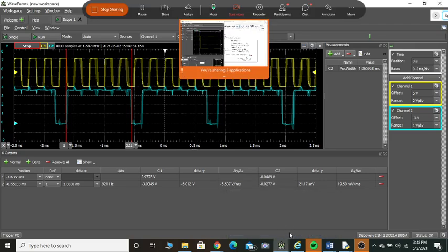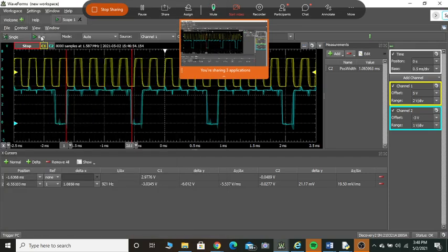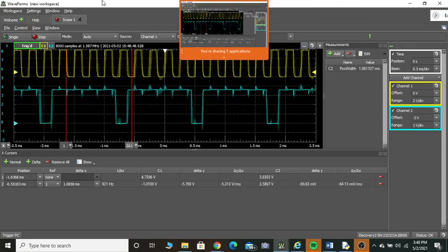Of course, one way of getting a proper trigger signal is to ensure that you apply 3 volt, forget about the offset. Otherwise, you can apply 3 volt and maybe apply a 4 volt or maybe a 2 volt offset. So this is also fine. This is also fine if you just start running. You can see if I run this also, it's coming.